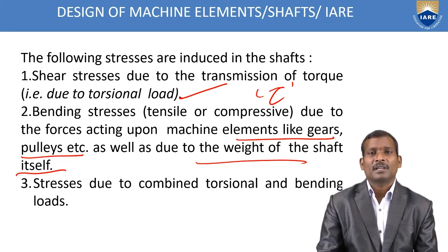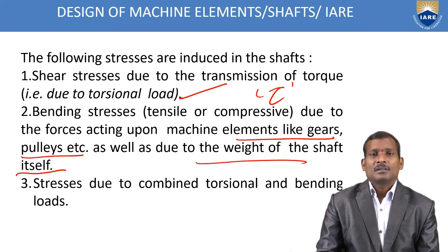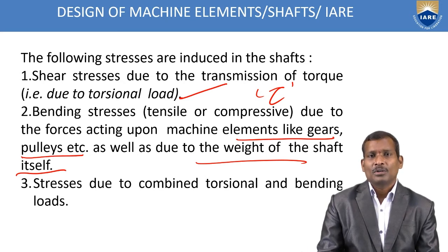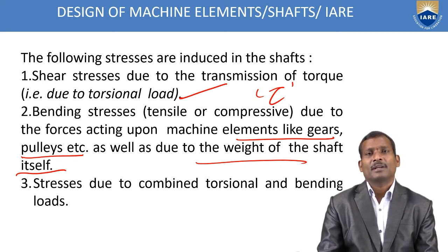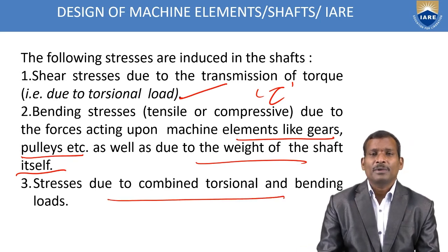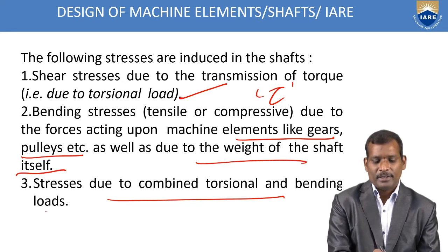Sometimes 2-3 gears and pulleys will be mounted on a shaft for transmission. In that case, we need to calculate the bending loads and bending stresses. Also, due to the weight of the shaft, the bending moment will occur. And then there are stresses due to the combination of these two, torsional and bending moment.